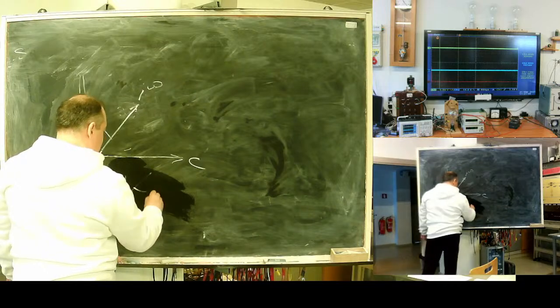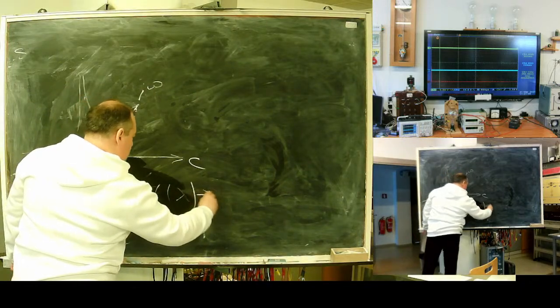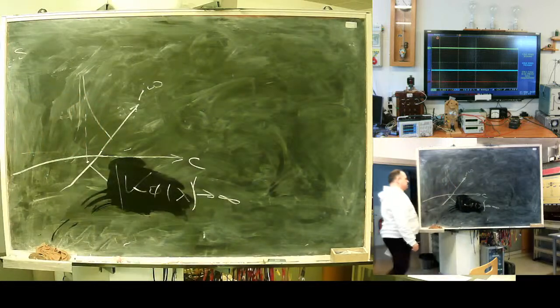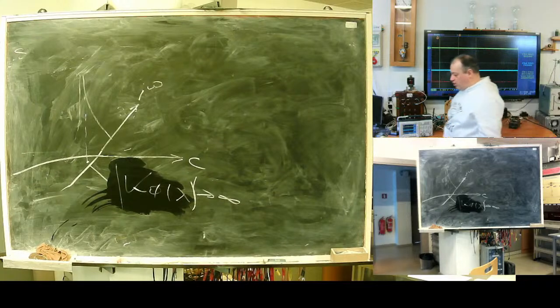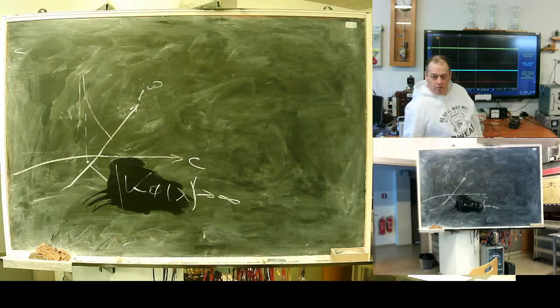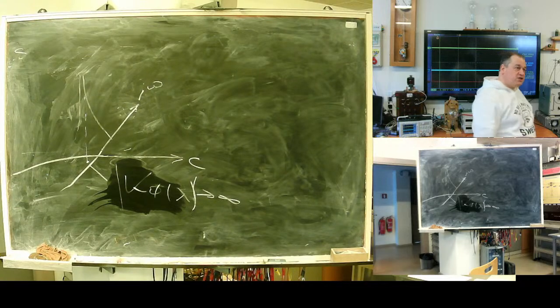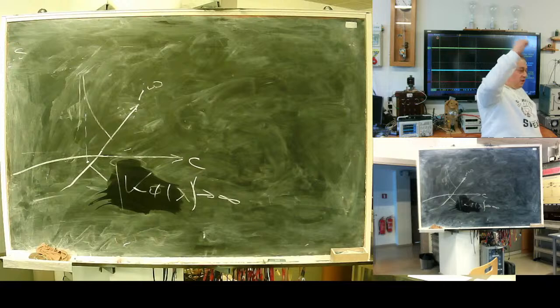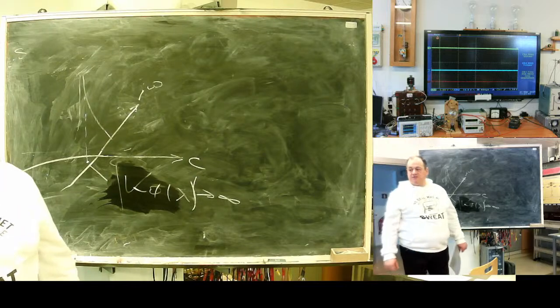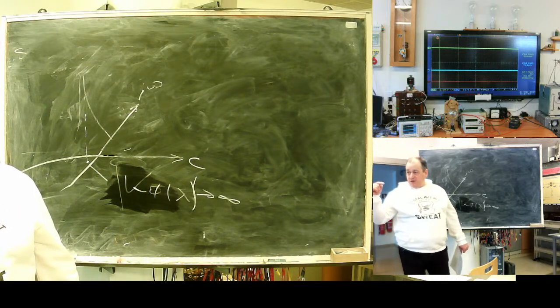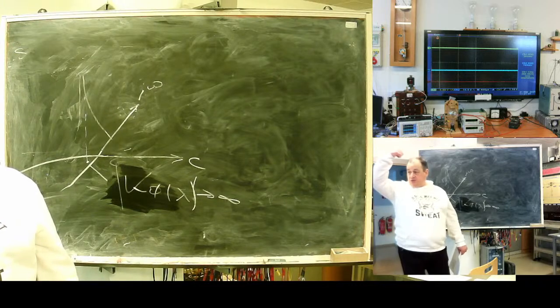It's a point when the zero at this lambda goes to infinity. This is correct, sorry. Poles. Remember such an idea, poles of a complex function. There are zeros, points where a complex function becomes 0, and poles. A pole is a point where the complex function goes to infinity. Roots of the characteristic equation are points where the denominator of the transfer function becomes 0 and the transfer function goes to infinity.